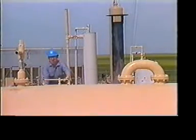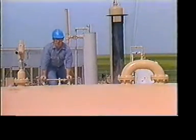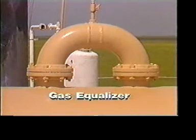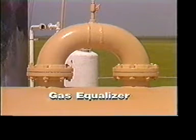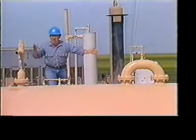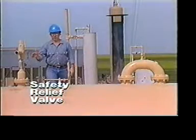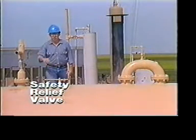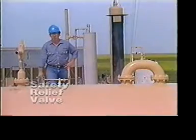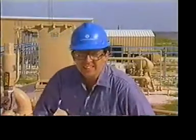Now, up here on the top of the treater, we find the gas equalizer line. This pipe allows gas pressure to be equalized between the internal sections of the treater. Now, relatively close to that line is a safety relief valve, which relieves excessive pressure in the treater. Sometimes a rupture disc will be used in conjunction with the safety relief valve.